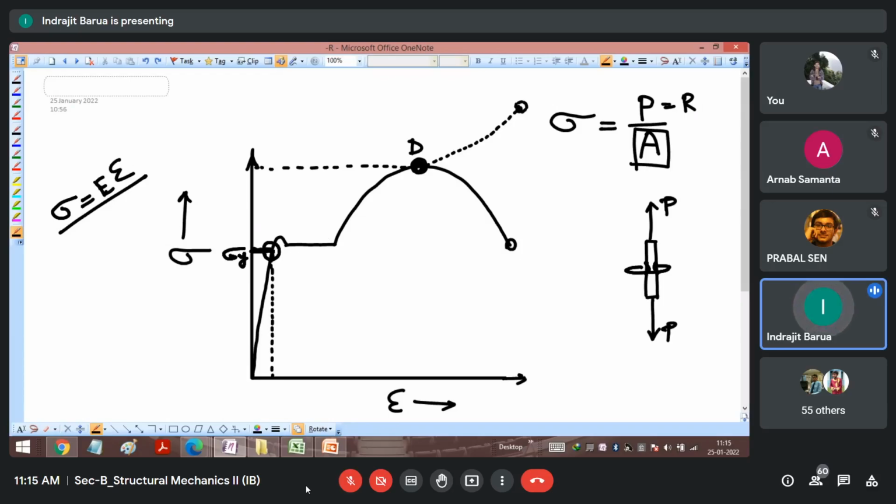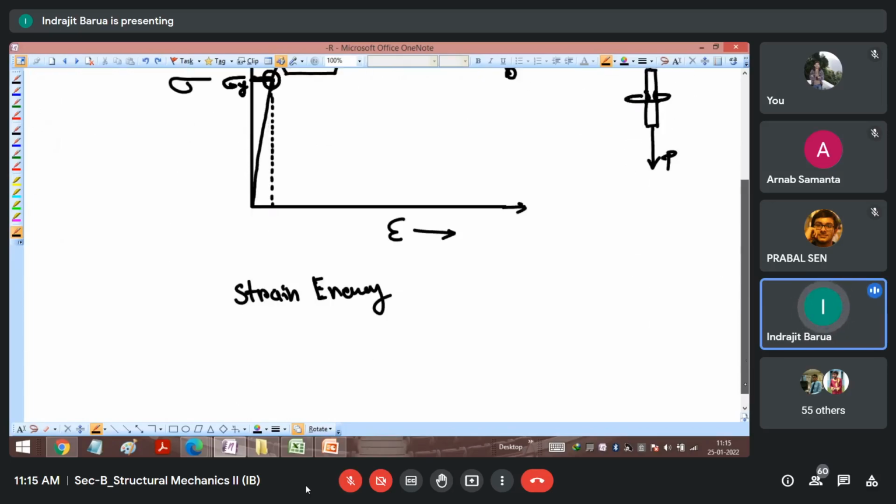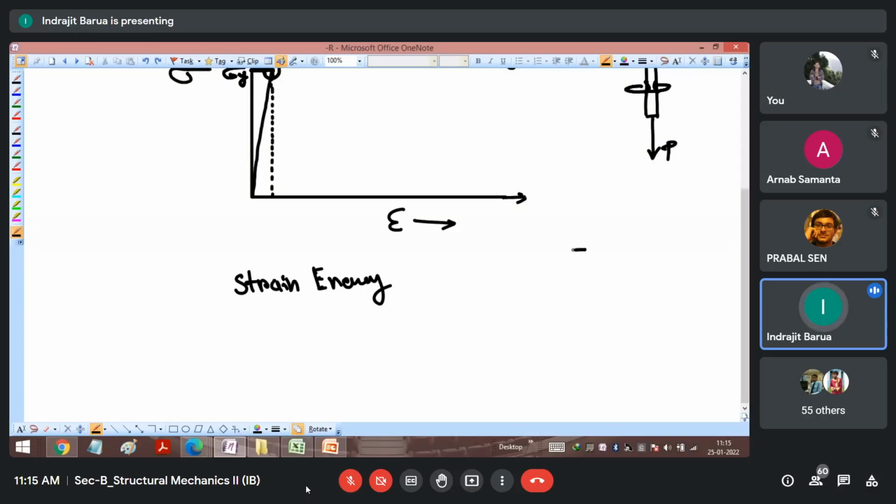With respect to that, I know that Hooke's law is valid, so our relationship is totally linear. If I use this with respect to the Young's modulus of a material, I can design things. I know this much is the stress up to which it can take, and the applied stress is something which I can calculate. So basically, always what I want to do is see how much is the sigma allowable and how much is the sigma which is working.